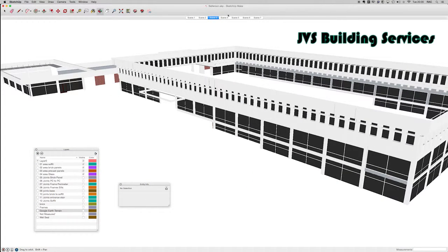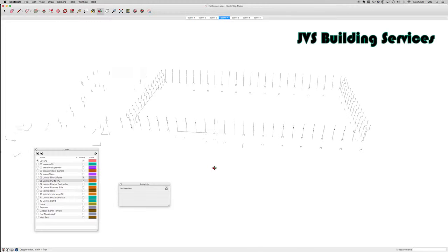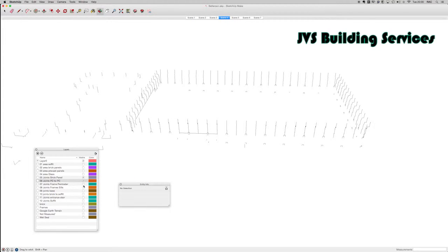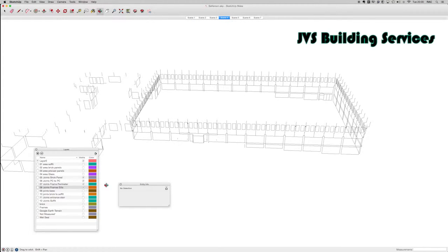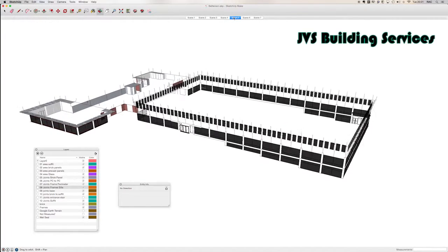There are layers in this drawing for all the sealant joints also. There's the joints between the brick panels. Here's the joints between all the precast building elements. And there are 2 layers for the window and door frame perimeter joints. And there's others. With this model, cost analysis for virtually any purpose is benefited.